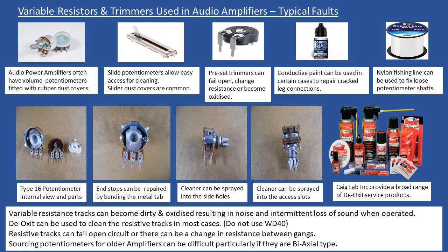So again, when you think back, maybe you had a rear heated window in a car, sometimes that resistive track got damaged. So what you could then use is some conductive paint to repair that. So what I'm talking about here is I'm not using conductive paint to provide a mechanical high stress repair, right? Because that's not going to work.